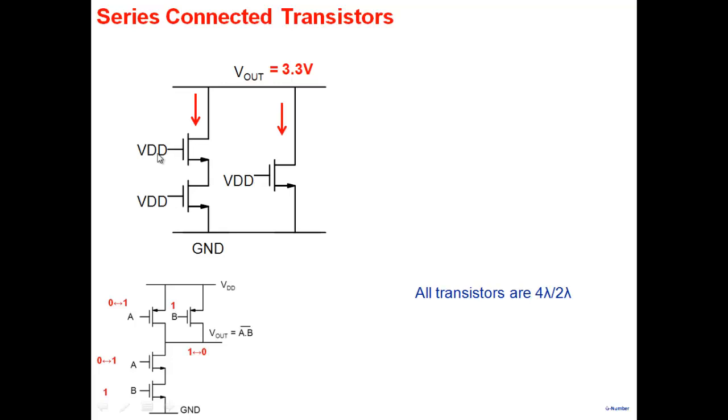So when I apply VDD here, VDD here, VDD here, which means two NMOSs connected in series here, with both connected to VDD. The current here is half as much as this. If I put this as 4 lambda and 4 lambda and 4 lambda here.